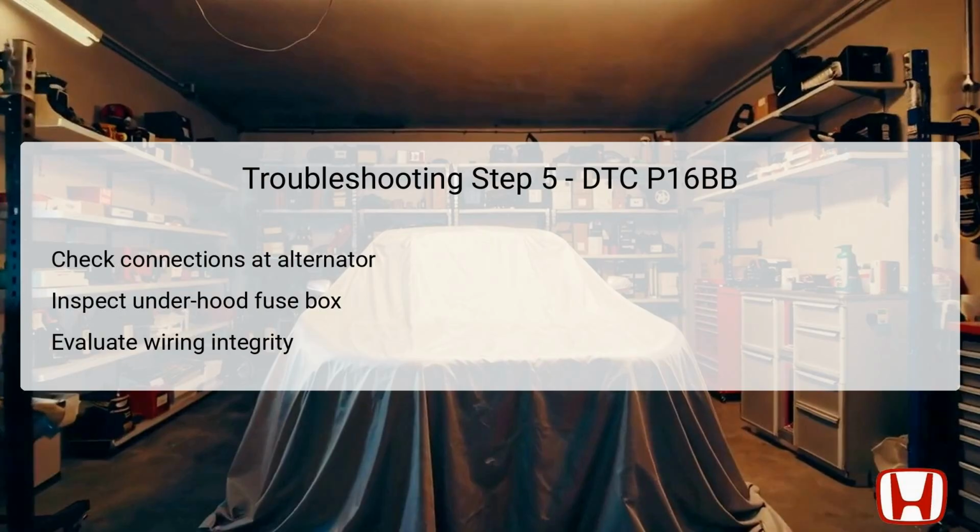This evaluation process is central to identifying any visible faults, and if found, necessary repairs should be made before continuing with further diagnostic steps. Should the connections pass this inspection, we proceed to check the integrity of the wiring harness between the alternator and the fuse box.